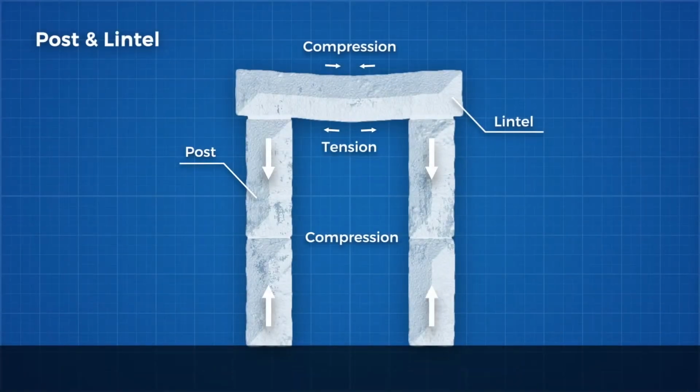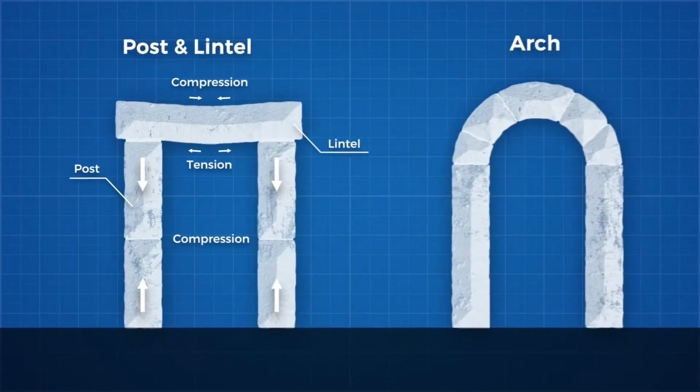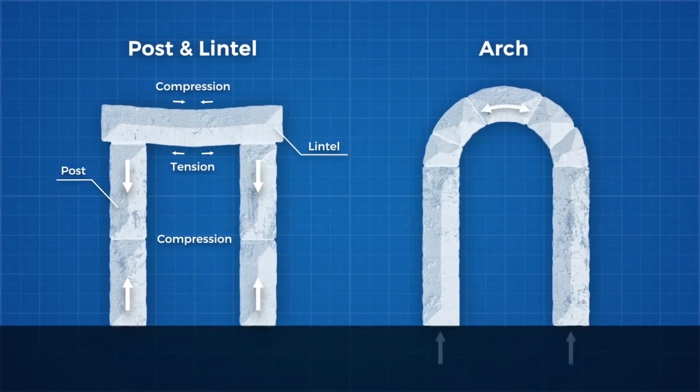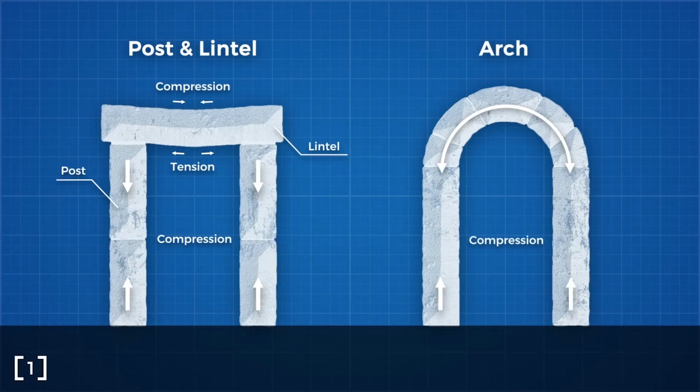It is able to sustain loads solely by compression. It is a structure whose geometry, perhaps better than any other, epitomizes the ingenuity of masonry constructions. In order to erect an arch with bricks or stone voussoirs, the individual masonry elements must be placed with radial joints to prevent shear slippage.